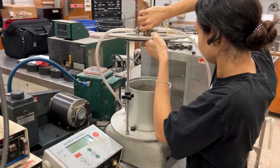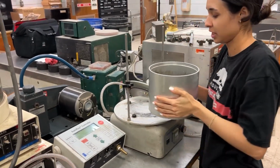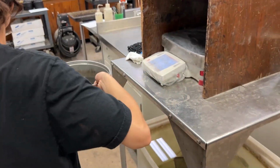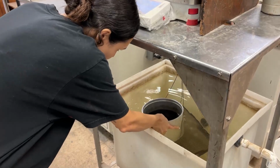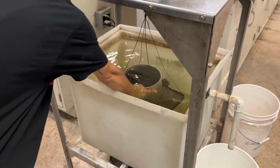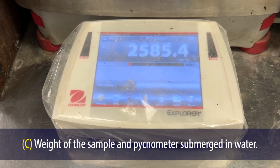Next, release the pycnometer from the shaker table. Having vacuumed and vibrated the sample for 15 minutes, we can be assured there are 0 air voids in the asphalt sample. At this time, make sure our balance is zeroed out. The water temperature is at 25 plus or minus 1 degree Celsius, and the water is up to the overflow outlet. Place the pycnometer onto the suspension apparatus and slowly immerse it into the water bath for 10 plus or minus 1 minute. Determine and record the mass as C.